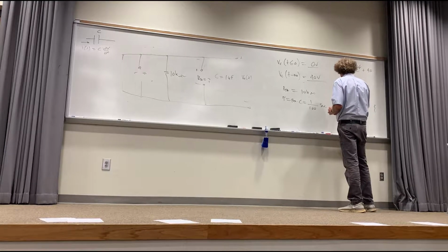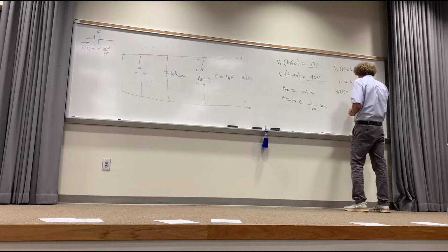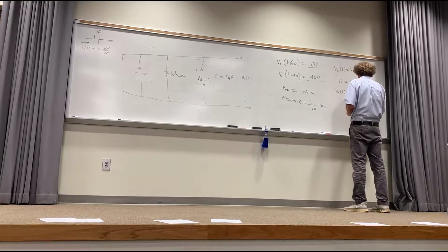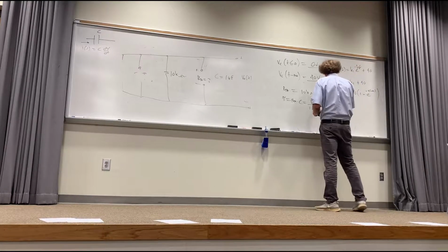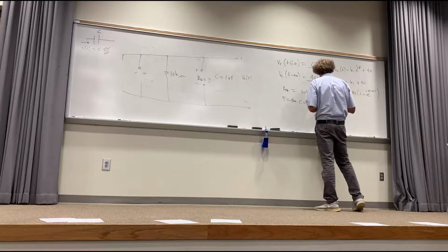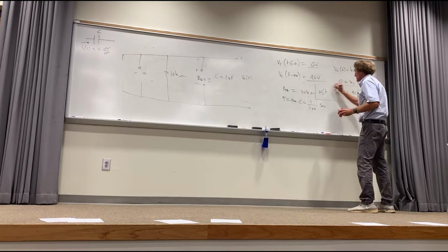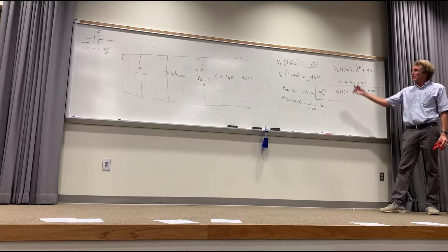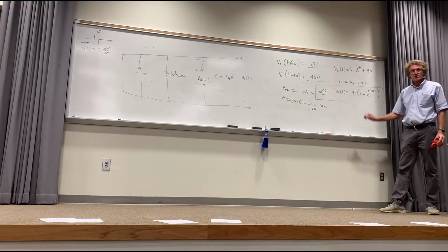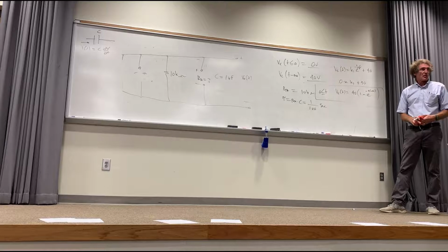All right. Now, that means Vc of t will be equal to 40, right? And it's going to be 1 minus e to the minus t, times 100 if I put in the actual value for tau. And this would be true for t greater than or equal to 0. That would be the solution. Do you all agree with me, class? It's very straightforward, and it doesn't matter the order you get that information, because it's just applied here. That's all. Got me on that?